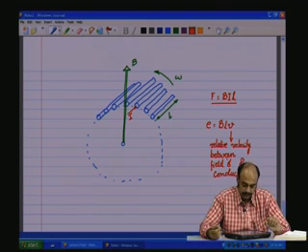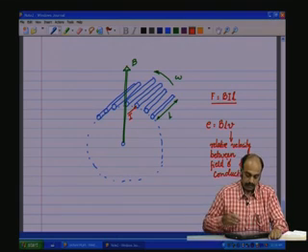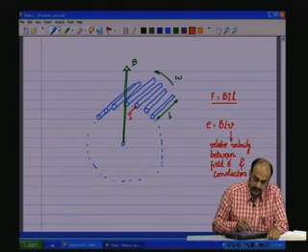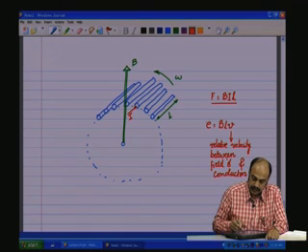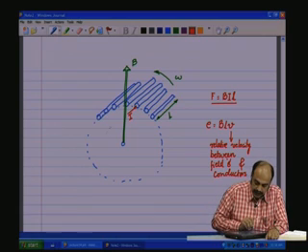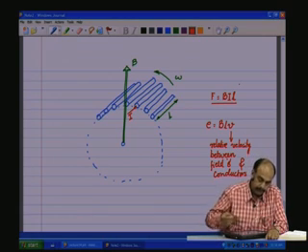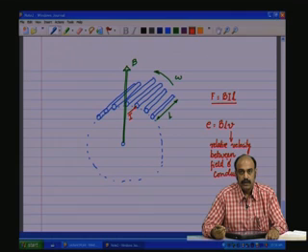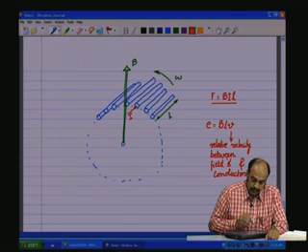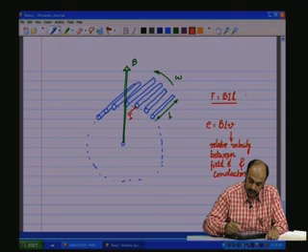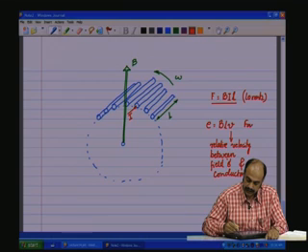So, first of all, how do we make the conductors rotate, or how do we create this relative velocity? Because that is what is going to induce a voltage on the rotor conductors, and that is going to create a current I, and therefore, B I L. There will be a torque on the conductor which will make it move. So, this would be the Lorentz force, and this is the Faraday law.